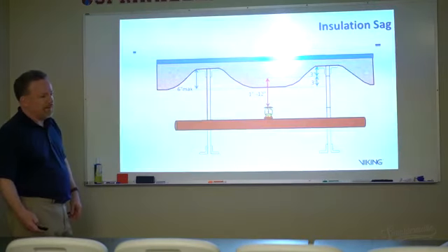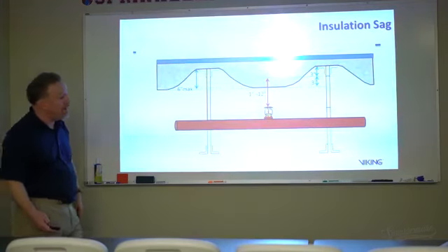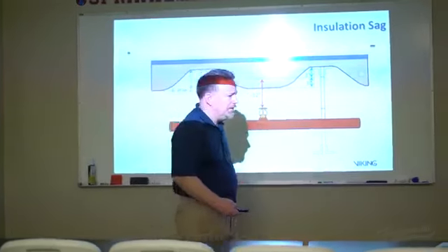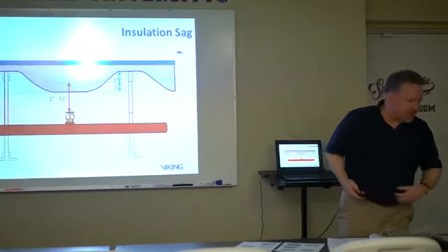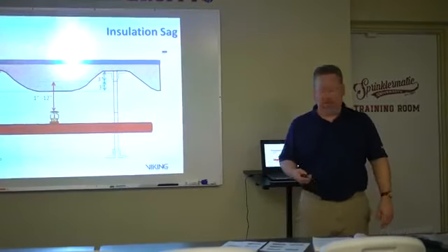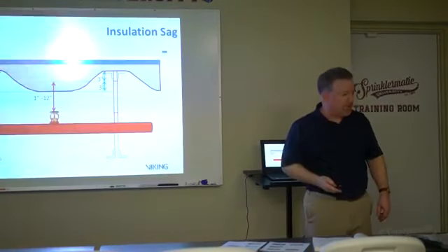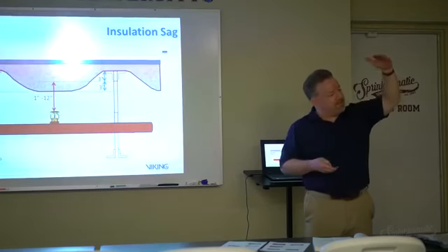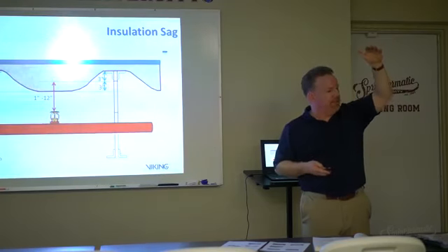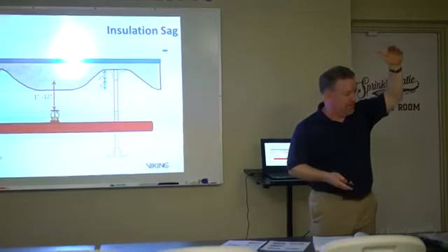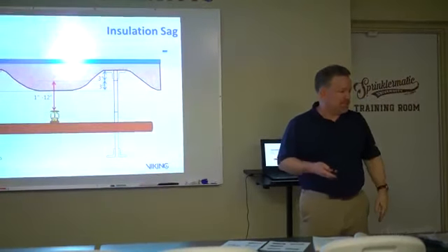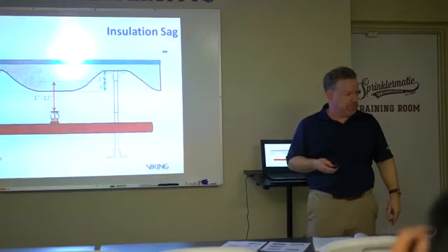Closer to 24 inches. Pardon? Closer to 24 inches. 24 inches where? From the ceiling. 24-inch gap from the ceiling. There's got to be a 24-inch gap between that and the ceiling? No, it's not 24, but it doesn't have to be. Okay, that's what I'm saying. There's a maximum that it can be in some cases. Flat smooth ceilings, I think, are 22.